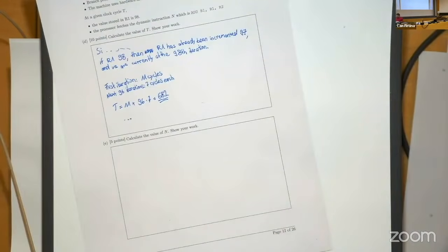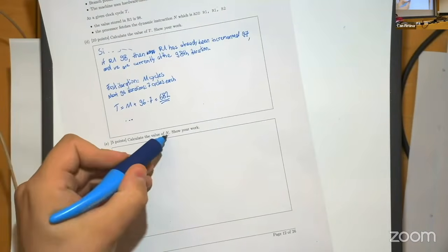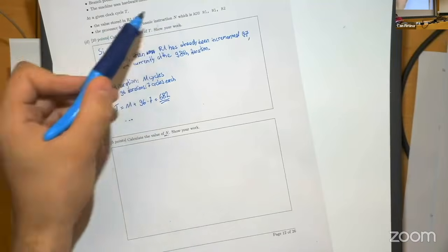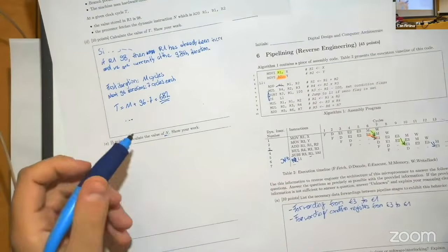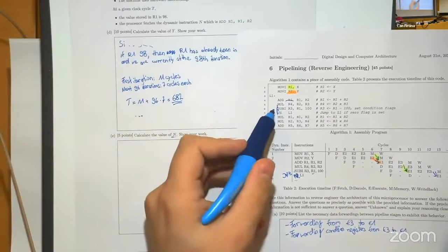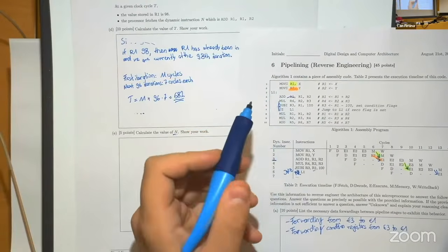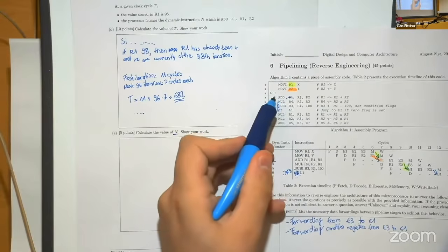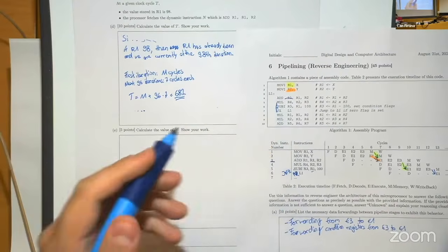All right. So finally, a bit of an easy question. We should calculate n. So this is the dynamic instruction number. So what we really asked is, given that we are in the 98th iteration, how many instructions have executed so far? We are fetching this one. What's the dynamic instruction number of this instruction when you're fetching it in the 98th iteration?